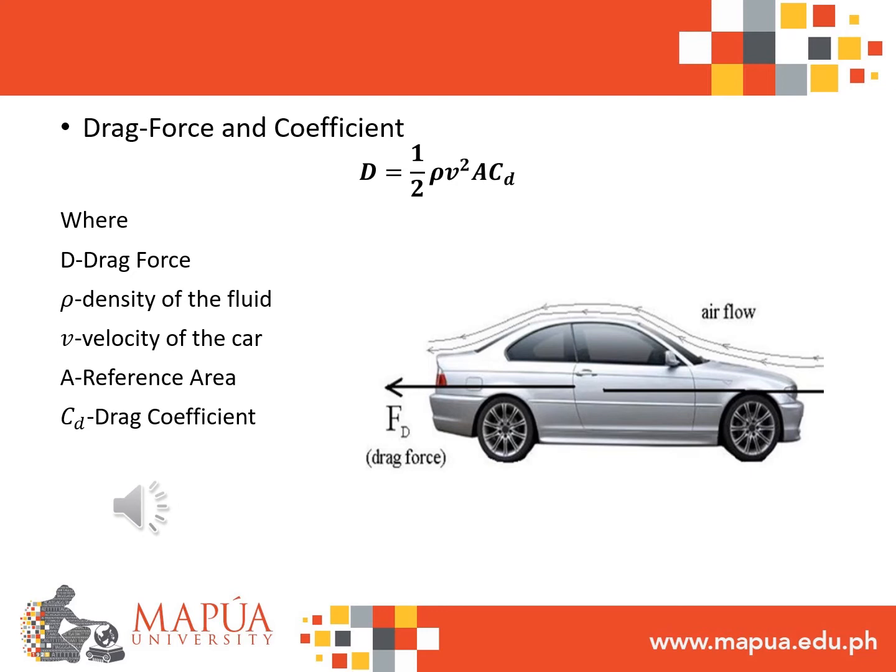Another important parameter to consider when it comes to designing the external body of the vehicle is the reference area. When the reference area of the vehicle is large, the drag force that will be induced will also be large, and if the reference area is small, then the drag force will be less. The density of the surrounding fluid also affects the drag force. The denser the fluid is, the higher the drag force that can be induced.